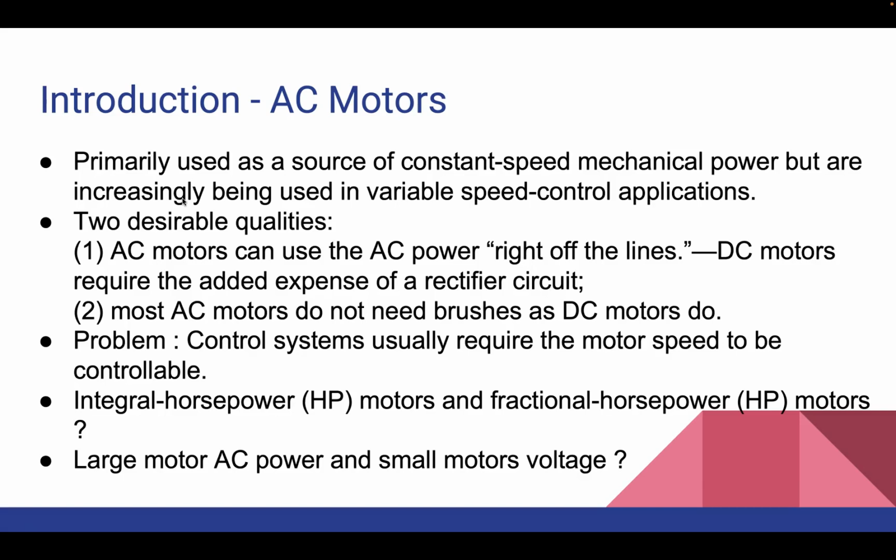However, despite these advantages that I mentioned, there's a challenge when using AC motors in control systems. While AC motors are highly efficient, they typically operate at a constant speed, which may not suit all applications. Achieving precise speed control requires adjusting both voltage and frequency, which is a task usually accomplished through specialized electronic speed control circuitry, such as volts-per-hertz drive circuits.